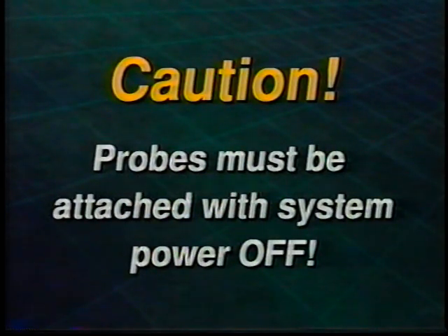The internal crystal detectors are sensitive to power surges. Installing or removing a probe with the power on could damage the detectors.